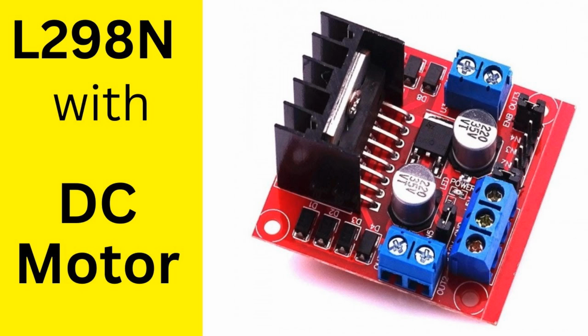Operation: FOC involves complex algorithms that dynamically adjust the motor's stator current to align with the rotor's magnetic field, providing smooth, continuous motion. FOC can be applied with both Hall sensors and sensorless configurations. Advantages: FOC provides superior efficiency, smoother operation, and more precise control over torque and speed compared to simple 6-step commutation. It also reduces noise and vibration and improves the motor's performance at low speeds.